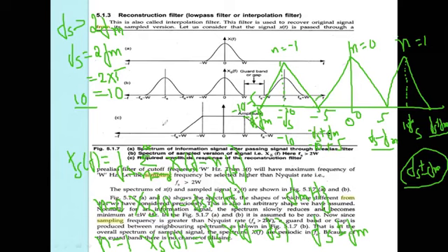Okay, but here there is no guard band, and this condition holds for Fs greater than 2Fm. In this case there is a gap in between the waveform of minus omega to omega, or minus Fm to Fm values. Now if we assume the second condition, Fs equal to 2Fm, there is no gap between the waveforms n equal to 0 and n equal to 1.